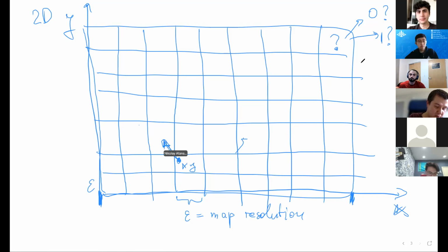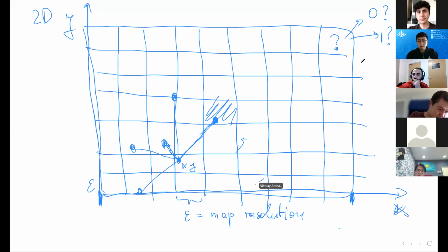Okay, so when we use our LiDAR sensor, it will give us some measurement to things in the environment, as we said, along these 4 beams. We can figure out the places where the LiDAR hit. It's very likely that these are occupied. We know the distance that the LiDAR measured and the angle at which it measured. We can figure out which box this corresponds to and mark this box as occupied. So let's say over here, over here, over here and over here.